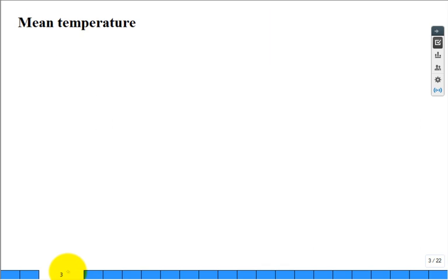Okay. Well, what about this mean temperature? I like to think of it as a simple expression and make that equivalent to a very accurate expression involving integration. What do you mean? Well, I have some energy flow rate. Remember last time for the mean velocity we had mass flow rate? I need some simple expression for the flow rate of internal energy. So a simple expression for the flow rate of internal energy would be the mass flow rate times the specific heat of the fluid times the temperature of the fluid. The mean temperature of the fluid, the appropriate average mean temperature of the fluid.